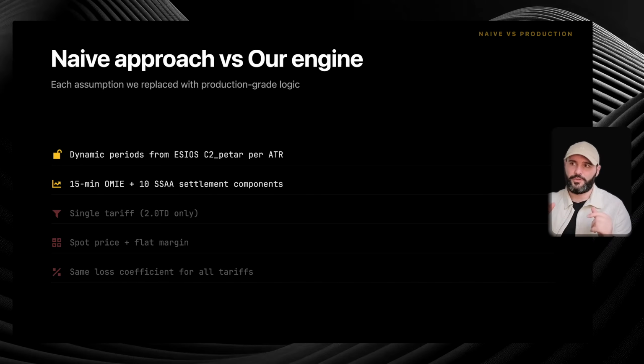For example, when you have solar energy being produced during the day, but there are some hotspots in the system that cannot be oversupplied with energy because the node doesn't have capacity to get into the transmission, part of those solar plants is being shut down.